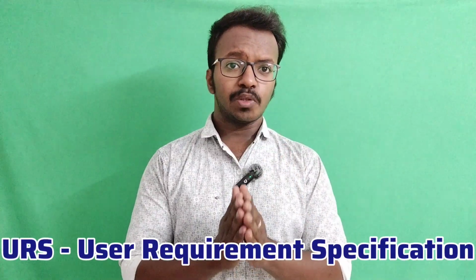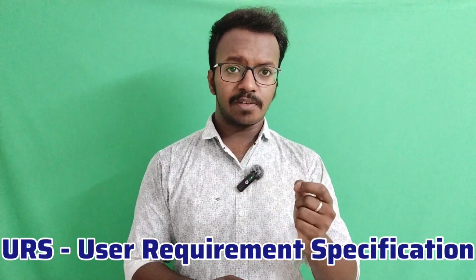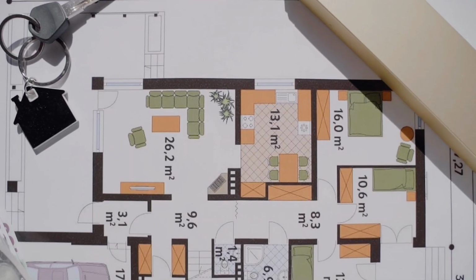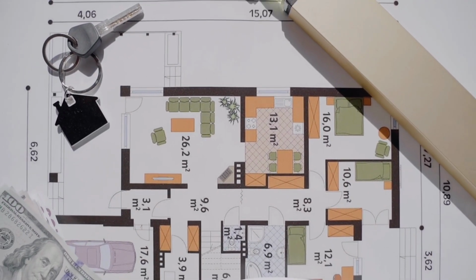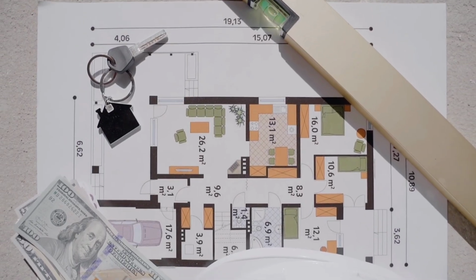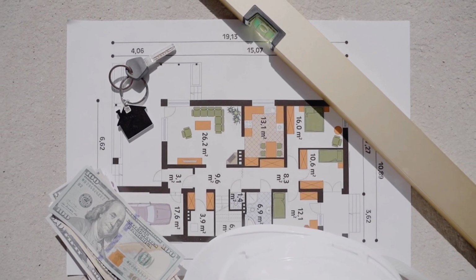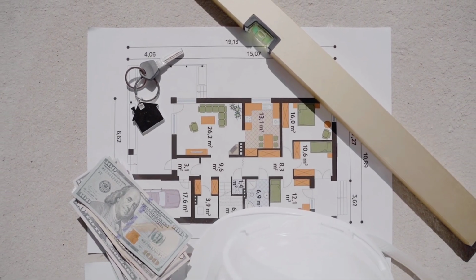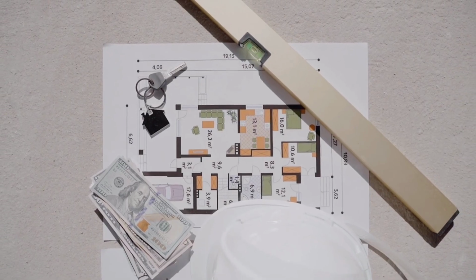This Part 4 specifies the process for clean room design, construction and startup. The first step, URS, user requirement specification. This URS clearly defines the expectations of the user or company from the system or equipment. Simply put, URS is a document expressing the expectations of users. For example, clean room design, layout, required equipment, and installation, everything.